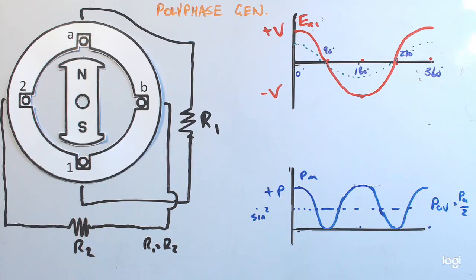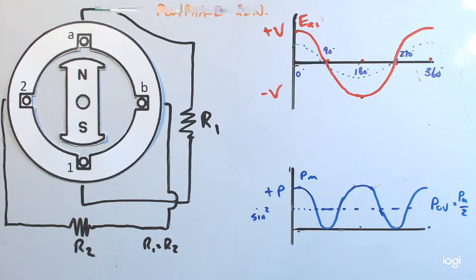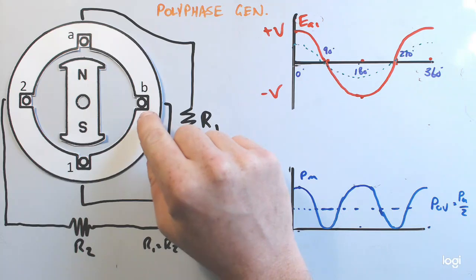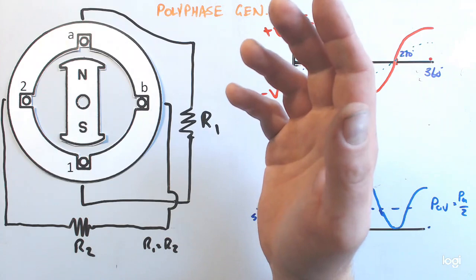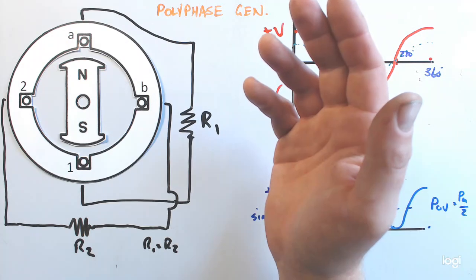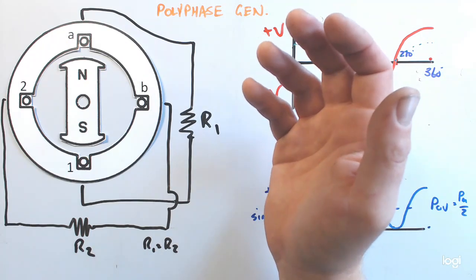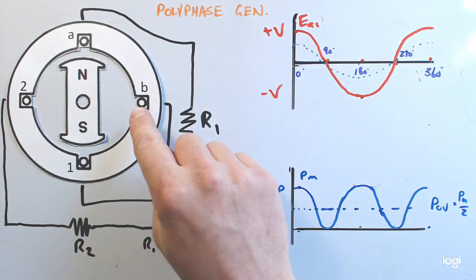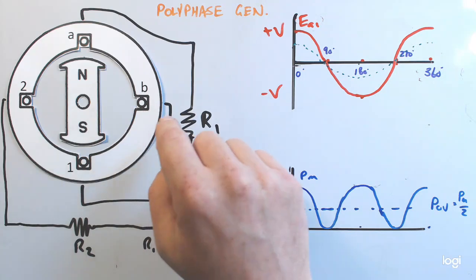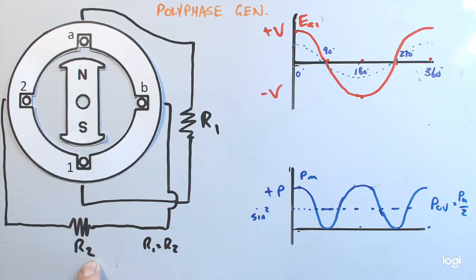Now, if that's the case, what have I done mechanically to change the generator? Well, as far as weight is concerned, I've made a negligible impact whatsoever on the actual stator, because what I've done here is I've carved out iron laminations, and I've replaced them with copper wire. So essentially the overall density of the generator remains unchanged. The total weight of the generator remains unchanged, and yet I've added a complete second separate generating coil, which means I can provide power to a separate load.